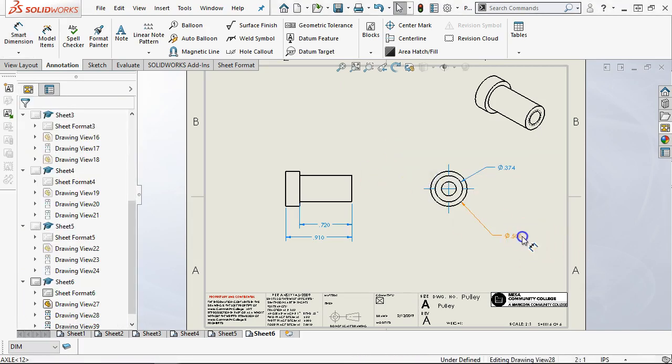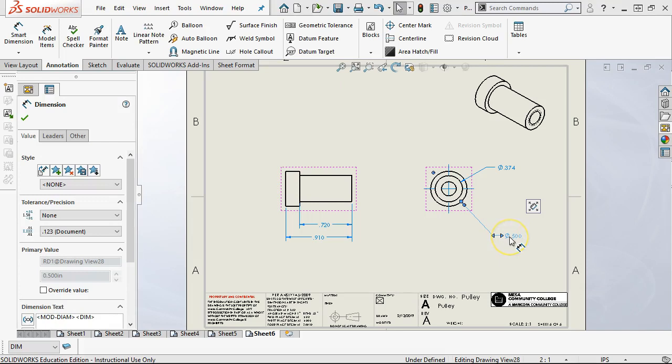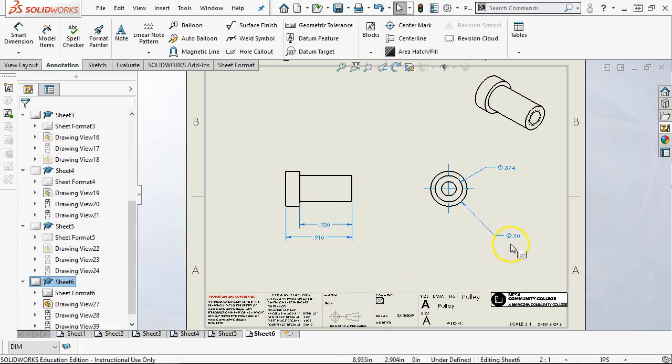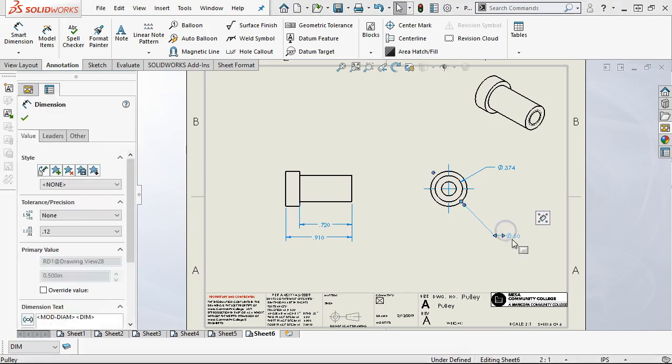All right, so this one I said really not that concerned with, and also on the spacer we really weren't that concerned with. I left those in 2 decimal places. So there comes a point that giving that extra tolerance, I can use bar stock. I can use my standard round stock, and if it's a little bit over, a little bit under, I'm telling the manufacturing that it doesn't matter.